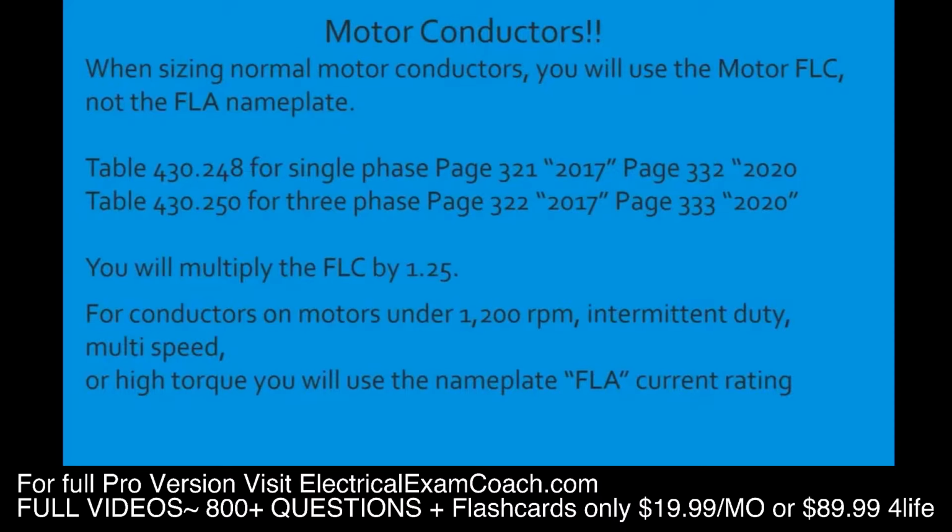If it's a normal motor conductor, you're going to multiply the FLC by 125%. If it's any one of these other motors, under 1200 RPM, intermittent duty, multi-speed, or high torque, and your question will say that in there, and I'm going to teach you how to watch for these red flags, you're actually going to use the FLA rating.